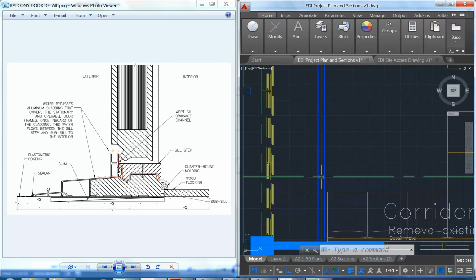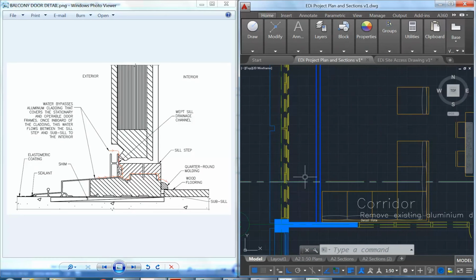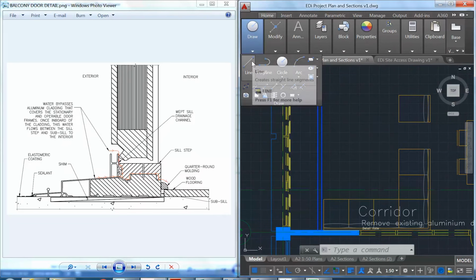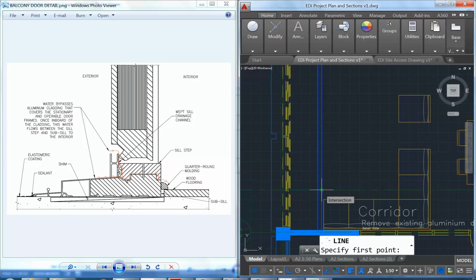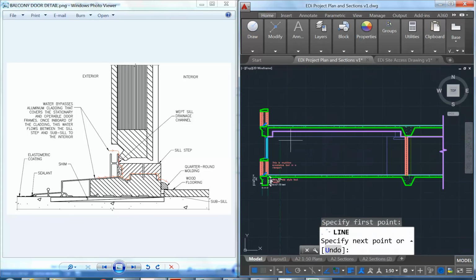Or so, well, it's a wall at the moment. It's going to have a door inserted into it, and it's not really worth drawing the plan until we have an idea how that's going to work in section anyway, if we're going to draw it with any detail in plan. And so now I can project lines from the floor plan, just going from the intersection of that wall line with the section line, and projecting it straight up to my section.